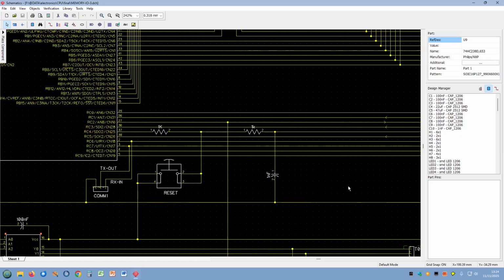But then it does that for 50 microseconds to reset everything, and then it turns it to an input. So then it's able to read the reset button, which also feeds out. But we have to have a resistor here so that the signal coming out here doesn't conflict with any possible signal coming out there when you first start up.